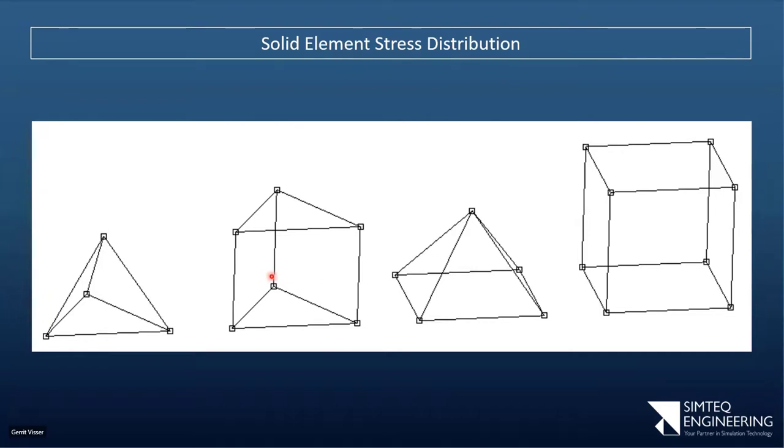This one, sometimes we'll use if we have a shaft and you want to model, let's say, a cylindrical shaft solid. Towards the inside, I might want to model with these kinds of elements in the center, but you have to be careful in which direction it's loaded. So in that case, if I extrude in thickness direction, I bend the shaft, it's actually in the direction this is good at. So that's okay. So what is the purpose of this element? That element is purely to transition from this to either these or those, and that one is about as hard to mesh as it is to mesh this one.